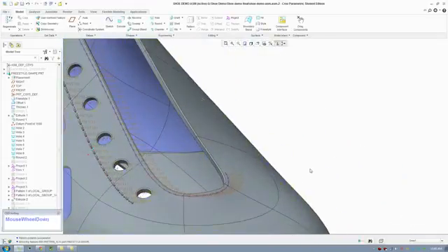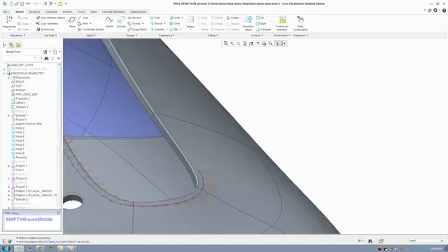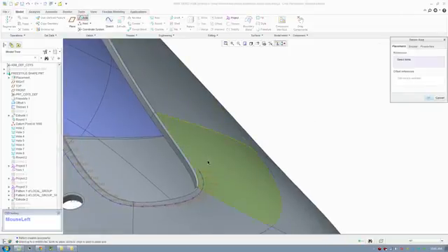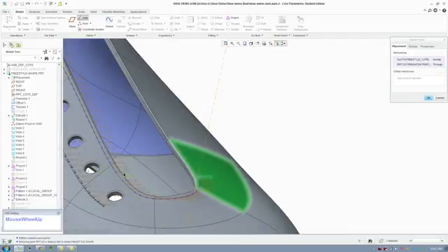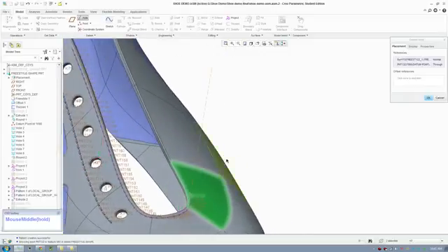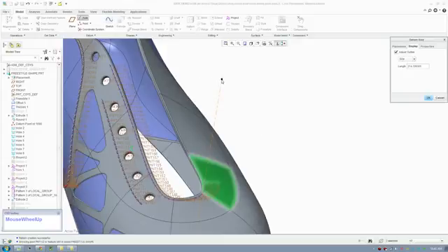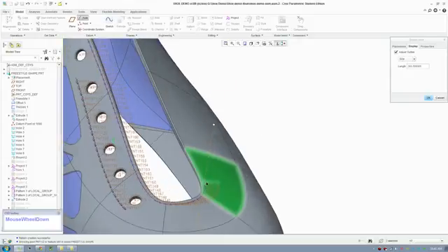Now another thing we need to do is create an axis. When we create this axis, make sure you select the surface and also the point. When you click the surface, it points up to normal, and this is really important to make sure your geometry is facing normal. And what's really handy is when you go to display, you can adjust the length of these datums so it's not messy.